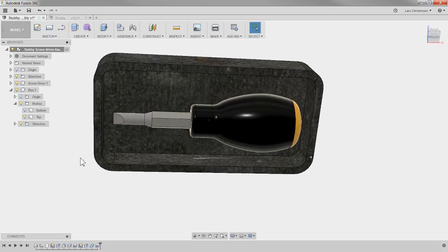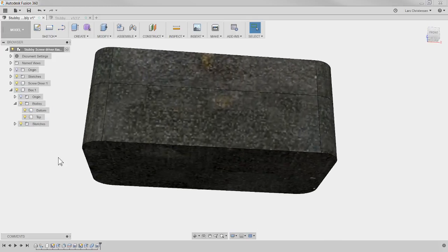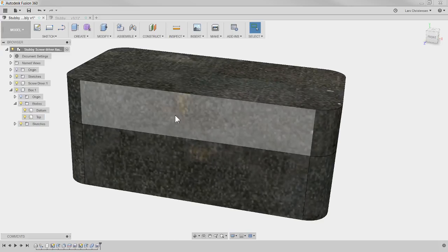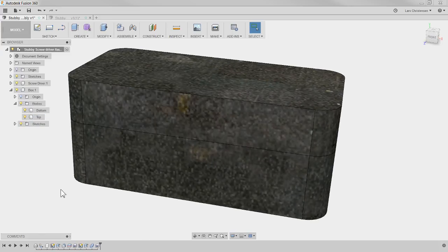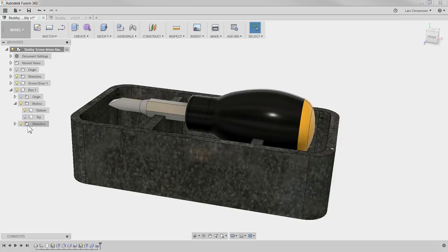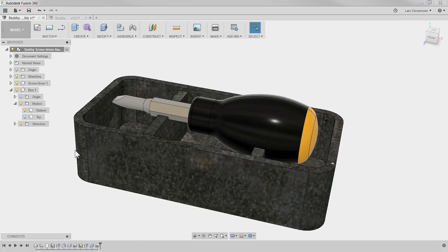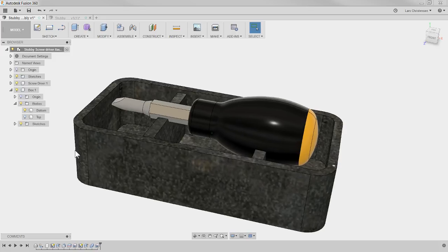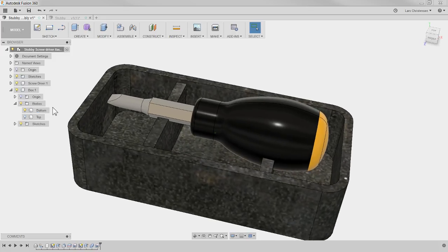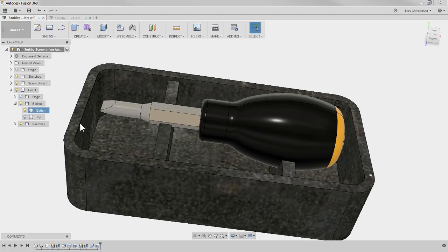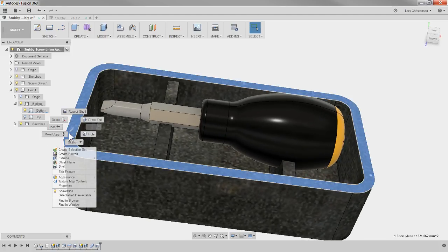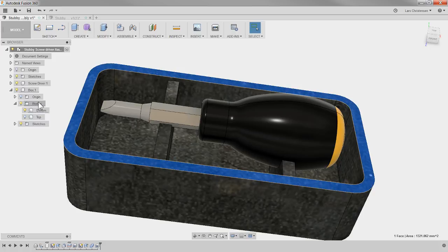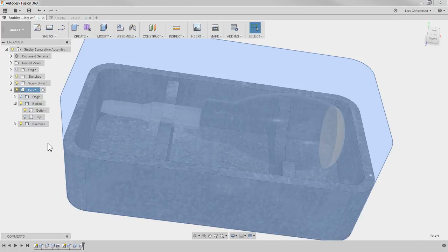Some people have asked me, when you have a box like this, right now this lid is just floating around, how can we create a lip that will be enclosed on? One trick would be to go back to the bottom or the top, wherever you want the lip to be. Open up a sketch, right click. Oh, and I want to make sure I'm in the box folder here.